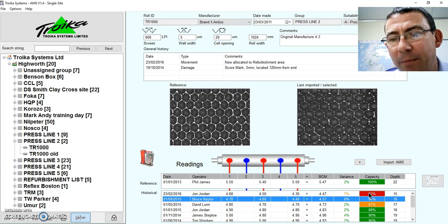How ridiculous. Much better that I take a proactive response and actually measure and know what I'm doing. If I know my volume, I know my ink rheology, and therefore my make ready time is reduced, my make ready waste is also reduced, and my productivity goes up.